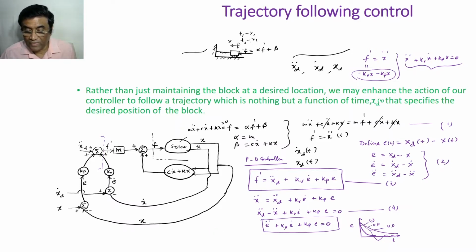Depending on the values of kp and kv the behavior will vary, but the most desired is of course kp and kv designed such that it is critically damped. But even otherwise, it will be either underdamped or overdamped, and the error in the steady state, virtual static state, means at t very, very large, larger than what you can imagine.